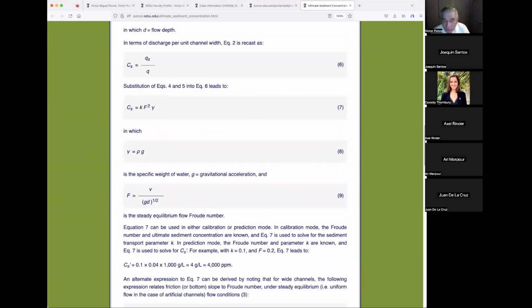And I should mention at this point that the D of the Froude number is the capital D. That's a theoretical definition of the Froude number. However, in practice, loosely, we talk about the lowercase d. The reason for that is that most calculations that we care to do are always per unit of channel width because the rivers are generally wide. So we're doing this per unit of channel width and then multiplying by the width of the channel, and bingo, that's it, we got the answer. That's a very common type of calculation.